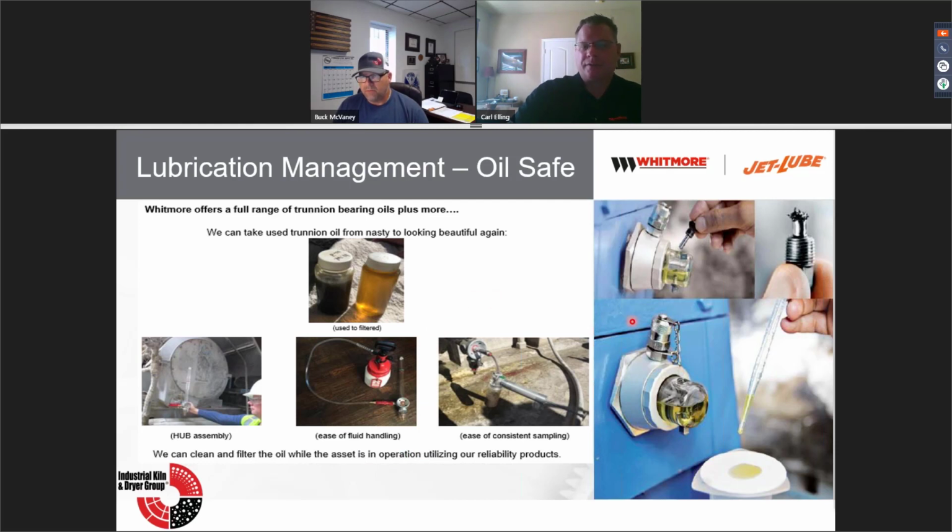And then if you've got some smaller gearboxes, you've got the same kind of capability of just having a visual sight reference. This is where the magnet and also the rust, if you do have rust in there, is. You can unscrew this just a little bit. There's an O-ring there where it will not leak. So you can rotate this over, take the magnet out of this one, rotate it up here, and then you can test for if you've got water in your oil. And your sampling port will remain there, and that provides you consistent sampling, so you can build a true representation as far as trend analysis.